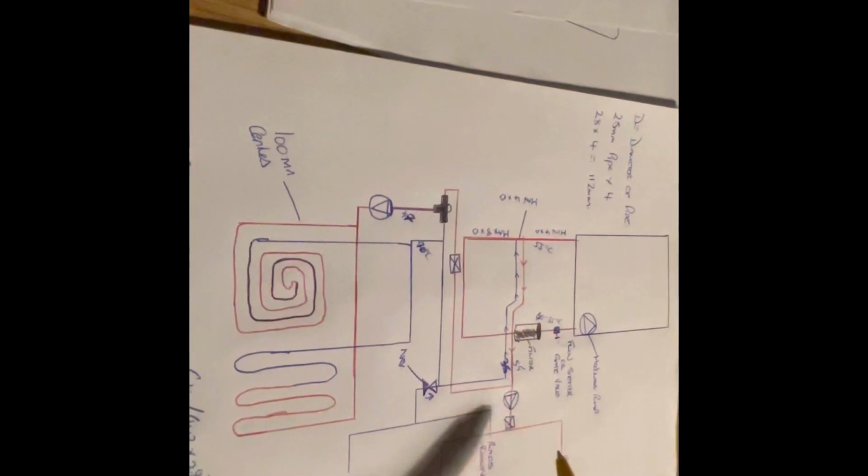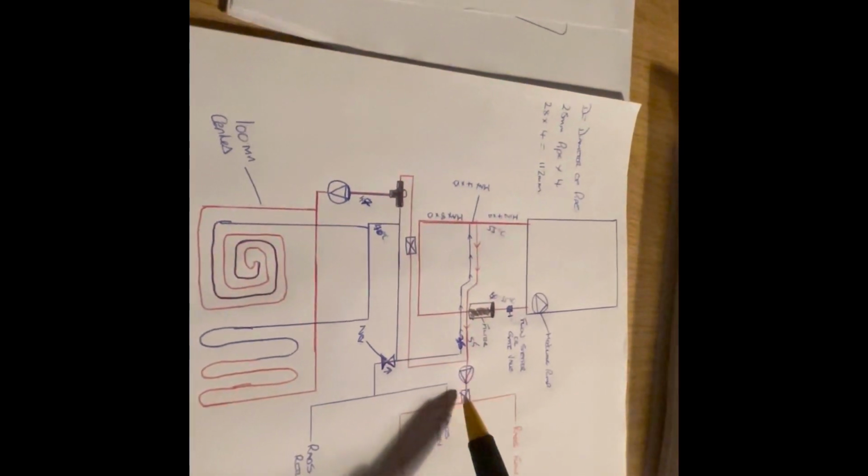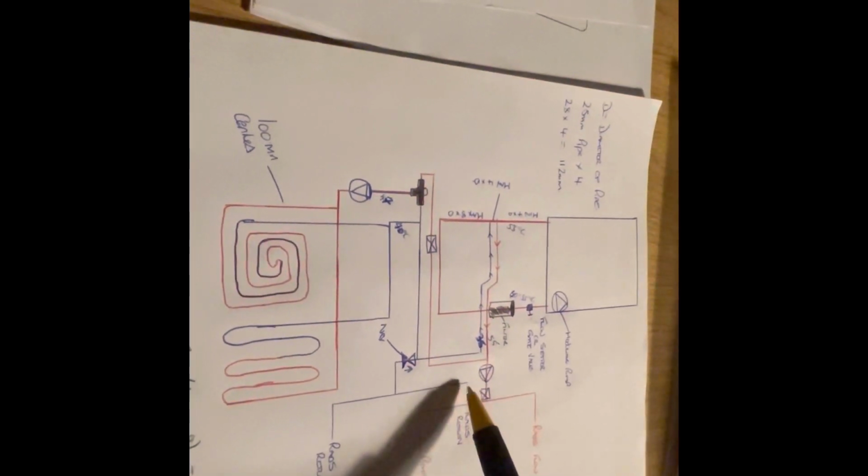The other thing is, if you understand how to design a system for lower flow temperatures, which is part of the new Part L regs that are coming in, if you can get a property to run on low temperature now, and all the DTs and everything match up and it's all okay, then you're kind of proving that that house is set to run on a heat pump. Because if you can run at the same temperature, it doesn't matter what the heat source is.